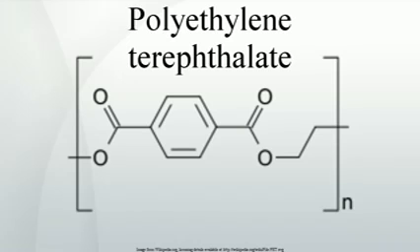Terephthalic acid process. In the terephthalic acid process, esterification of ethylene glycol and terephthalic acid is conducted directly at moderate pressure, 2.7 to 5.5 bar, and high temperature, 220 to 260 °C. Water is eliminated in the reaction, and it is also continuously removed by distillation.